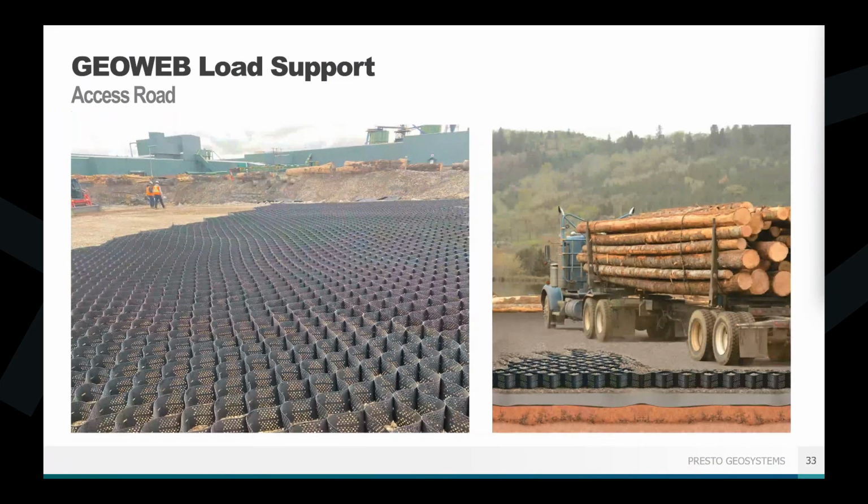One of the great design challenges for this particular project was a plan to manage stormwater and snowmelt. The engineer had called for large rock initially to help promote that stormwater infiltration, and had it sandwiched between layers of geotextiles to hold that rock in place to try and let that stormwater happen. It was becoming a whole thing. So we were able to come in, offer our value engineered solution.